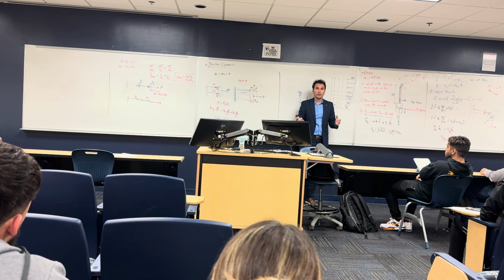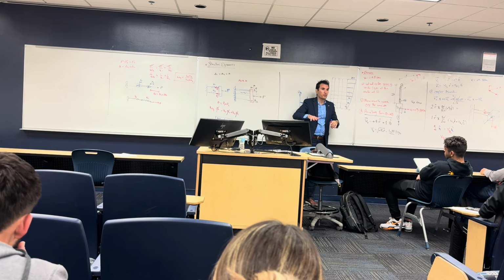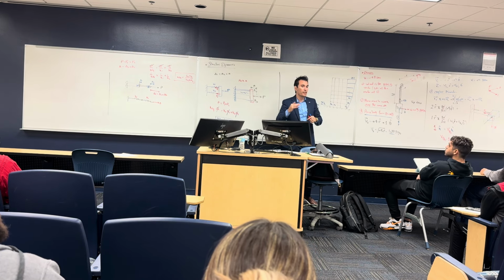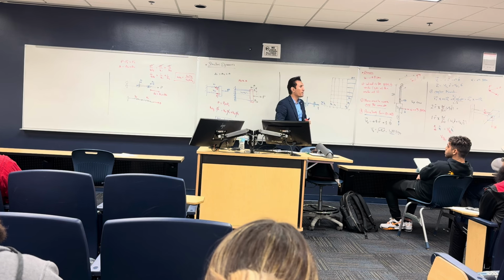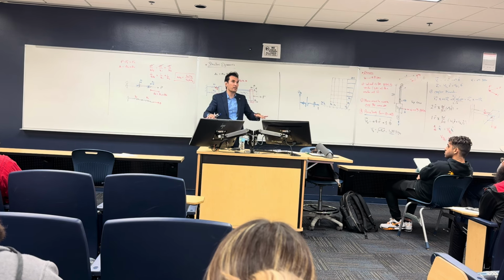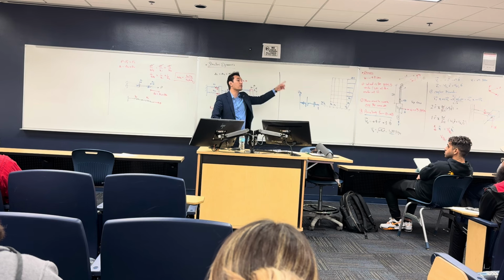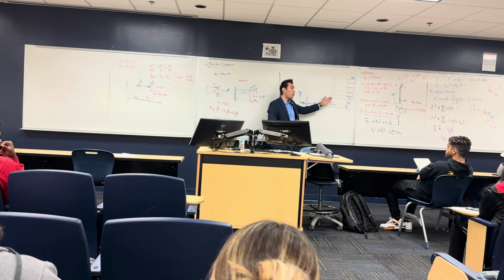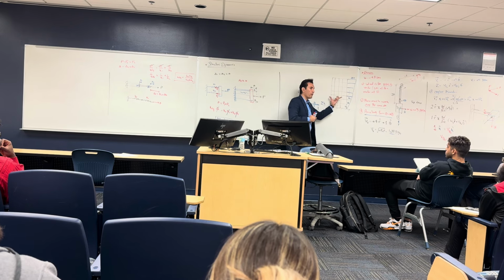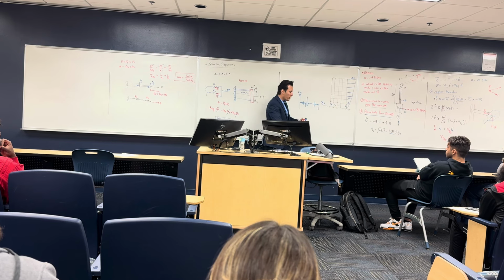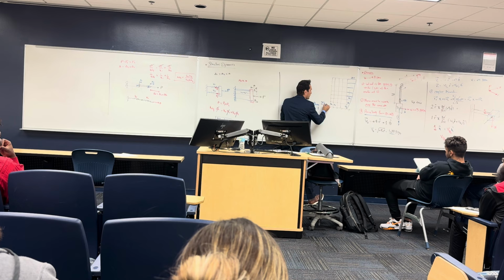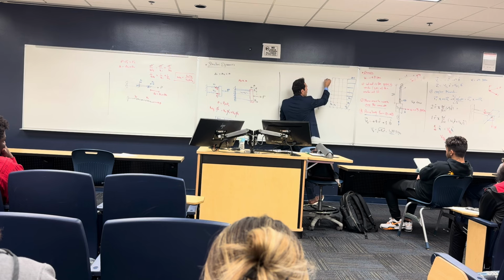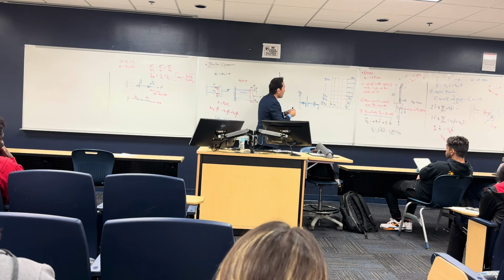When we design structures, if your slab has lots of holes, like you have an elevator or a stair and you need to make a hole in the slab, that decreases the stiffness of the slab and makes it less rigid. That's why the standards say that, based on the number of voids in your slab and the thickness of your slab, you can consider your slab as a rigid or as a flexible diaphragm, okay? So adding more beams is going to make your slab more rigid. Story number 1 is going to have the sum of all the K's here. Same thing with story number 2, K2, K3, up to the sum of Kn. All right, so we are done with one part.